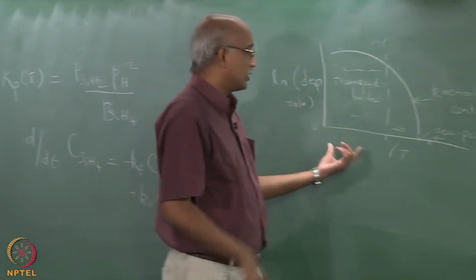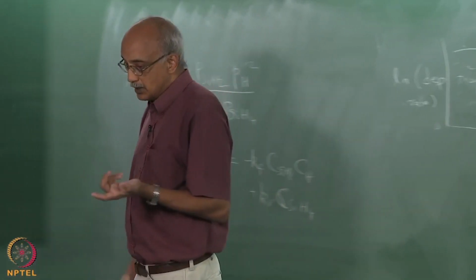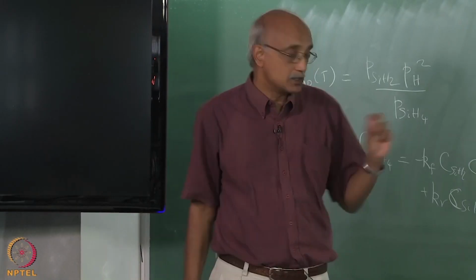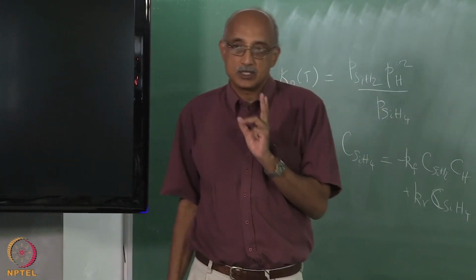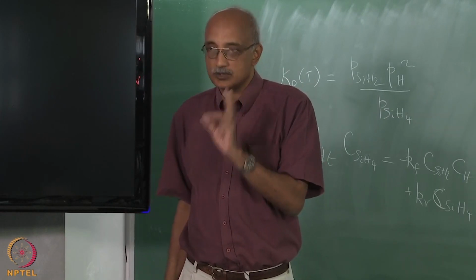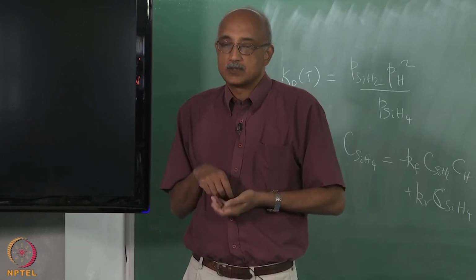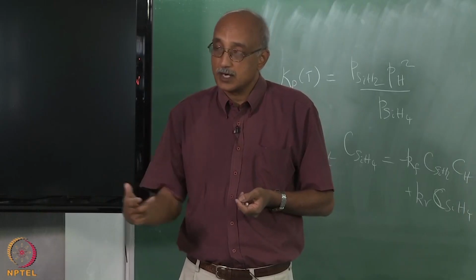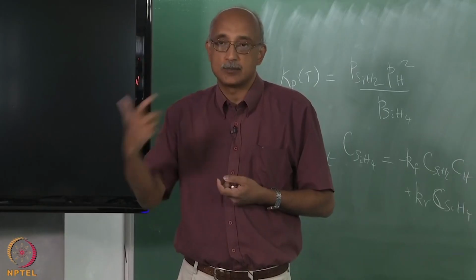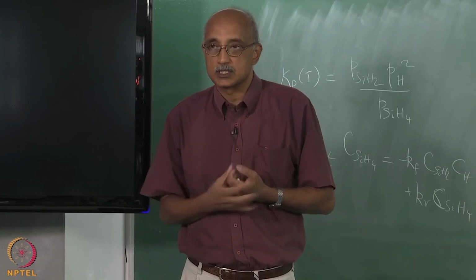So, what does it mean? What this means is, if you are in this high temperature regime where you are transport constrained, the design of the reactor must pay a lot of attention to the flow dynamics, because you are transport limited. That means you have to maximize and optimize your transport mechanisms. So, you have to ensure that the reactants are being fed in at the right rates, that all the flow patterns inside the reactor are being maintained absolutely stable. You cannot allow for even slight variations in the flow dynamics of the system.